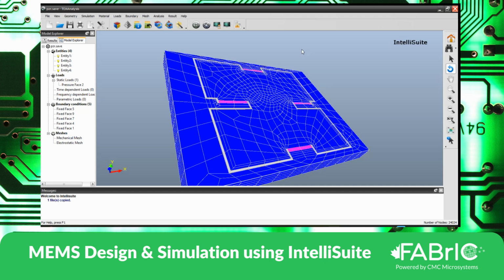You can get the VI characteristics, and based on that, you can extract the R. At the end of the simulation, you get the current density, the current in flow, and the potential drop. Based on that, you have to extract your R. So the software does not plot an R, but we can get a VI curve. Yes, you can get a VI curve.